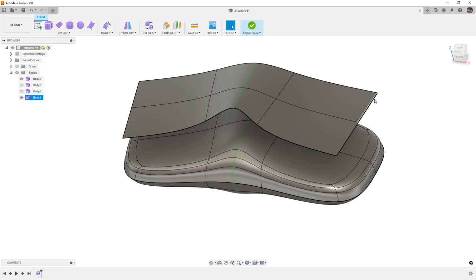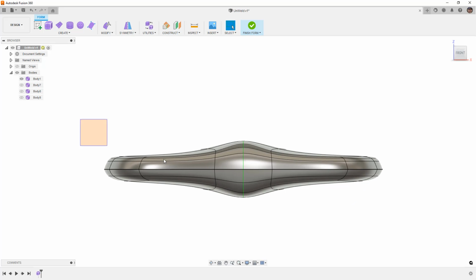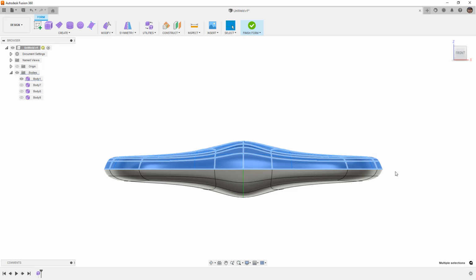These edges, this boundary here, is not going to quite match the boundary of the edge that we selected. And that's partially because there's more geometry here that is driving that. Now, there is a way to get around this, and that's to select all the way up to this crease. Now, if you try to do this before, if you do a box select and you try to do Control C and Control V, nothing happens.